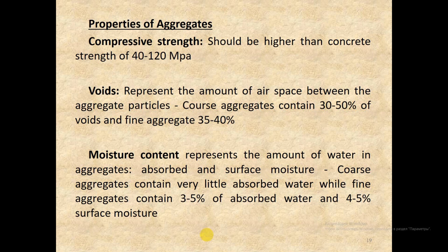Also, when delivered to site, aggregates should be tipped onto a concrete apron laid to falls. Partition walls to separate different aggregates are essential, and a sensible means of discharging aggregate should be developed.